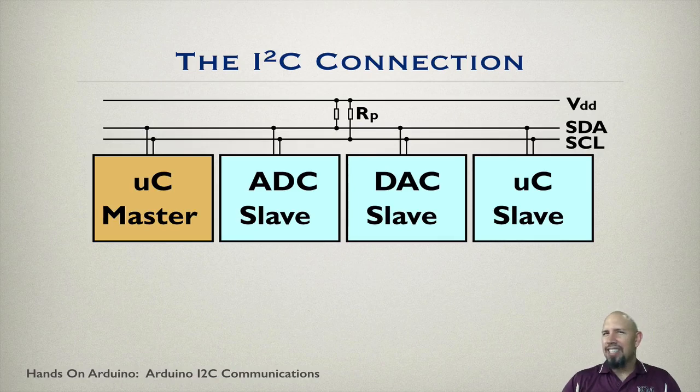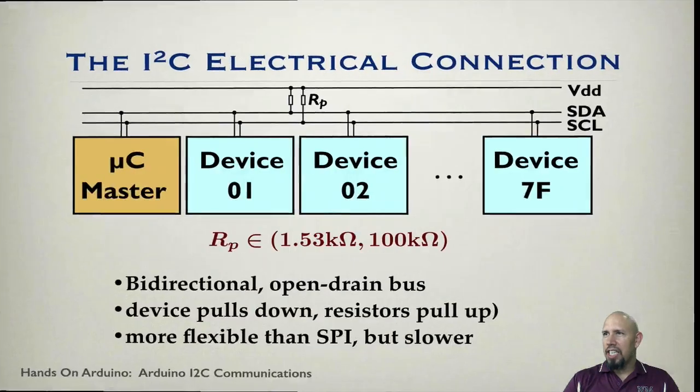So it's not exactly a two-wire interface. When we implement it, we're going to use 4 wires, because it's also good to have a ground that connects everything. Practically, you're probably never going to implement it using just 2 wires, but 2 wires are essentially all that are needed.